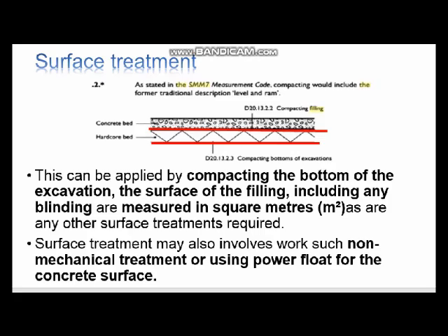And when you place the plastic membrane sheet on top of the hardcore bed for damp proofing purposes, it will not puncture the plastic, because sometimes hardcore bed can be quite sharp as it is made of broken bricks and some other recycled material.